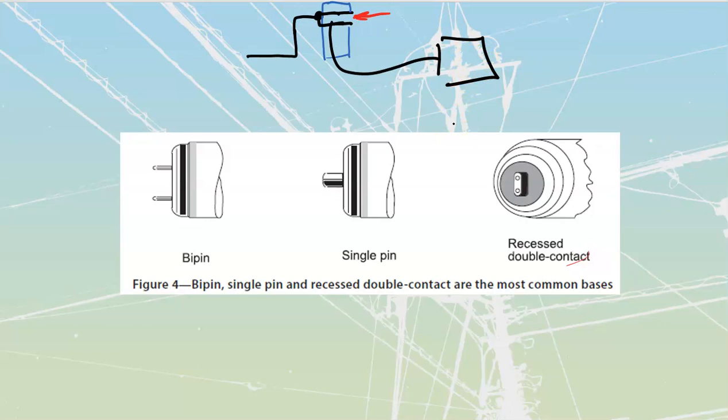If people have been screwing around with the lamps and changing them, and if they've changed the ballast, when somebody that doesn't know what they're doing takes out a ballast, there are multiple different ways you can rewire those ballasts, but not all of those are going to be the same. Some might work, they're just going to be dangerous. So be careful. If you open up one of these and you can see that somebody has taken those ballasts out and changed them, be careful that you're not exposing yourself to high values of voltage.